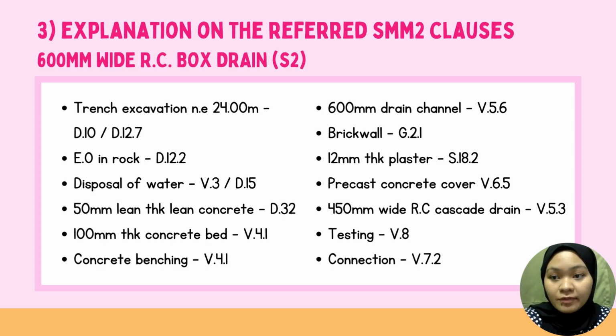Excavation in rock shall be so described. Rock is defined as any material met within excavation which is of such a nature or position that it can be removed only by means of wedges, levers, special blunt, power-operated hammers, drills and chisels, special attachments to mechanical plants such as rock breakers, rippers, hammers, chisels, explosives, or chemicals. Alternatively, rock may be given as extra over each of the various types of excavation.